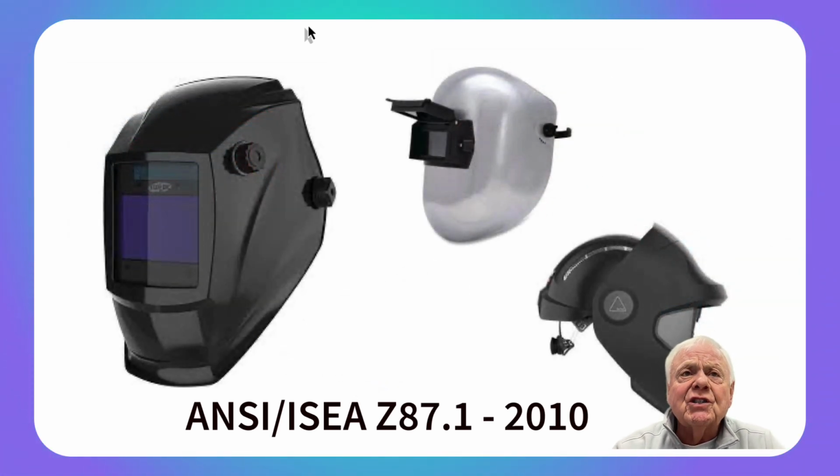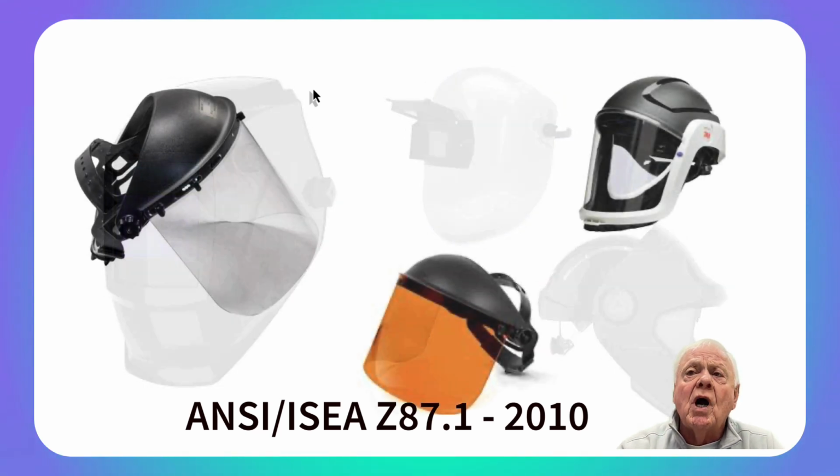On welding helmets, most of those, like the large helmet here, have an automatic window where the shade isn't necessary to be selected. The window will automatically adjust to the radiation that's being pointed toward the helmet. There are still some of the old helmets out there that you have to select the lens, so beware, make sure you select the appropriate lens. And in these cases, of course, you can usually get these kinds of devices that attach to a hard hat.